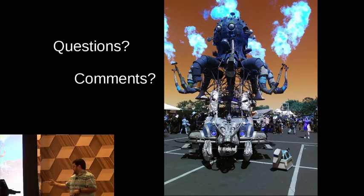And what you can do is, if you want to save a permanent program that will always run, like on the Bunny here, I just flipped the on switch and it started doing its thing. There's a couple of files that MicroPython specifically declares as, I will run this one first on startup, and I will run this one second on startup. And if you have your code in there to start whatever you want to do, they'll just run.